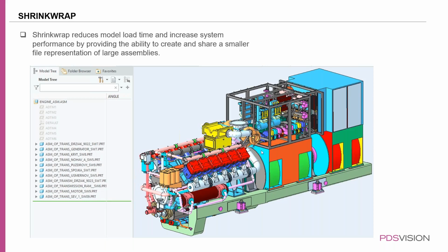So we've gone through and created these shrink wraps for each one of these, the generator, you can see all these different pieces that we've gone through and created all as shrink wrap. So when we look at this, it is literally a part instead of all individual items. A shrink wrap allows us to speed up the regeneration, but not lose anything visually, because we're still designing around this and we can see what we need to design to without using the full assembly,